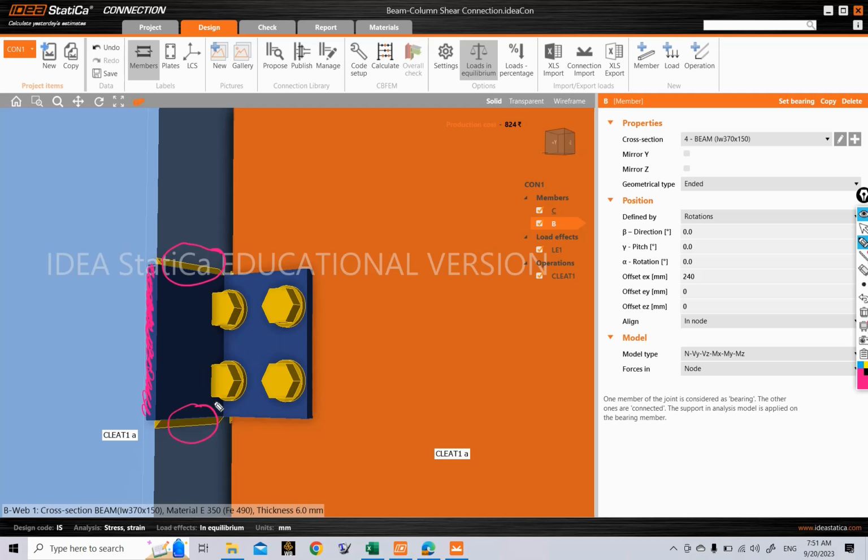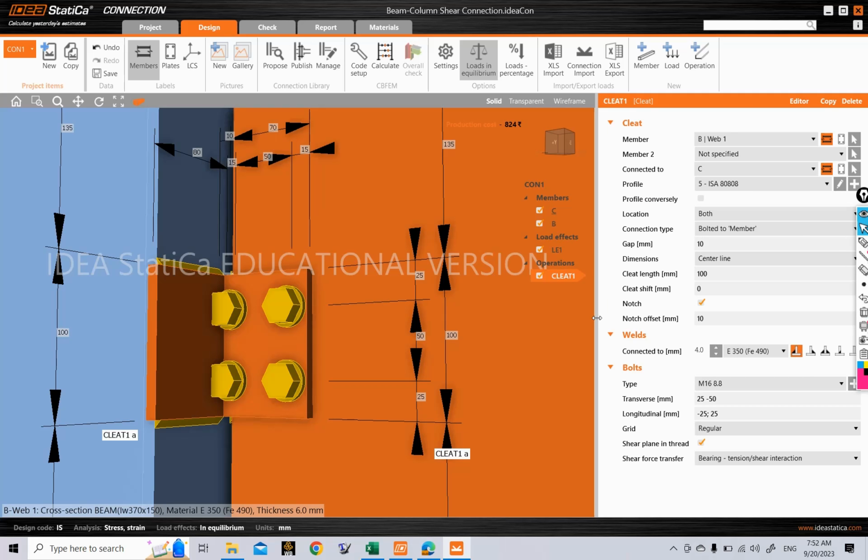So we have to change the parameters to make this, and also we used 2 bolts here, 1 bolt here and 1 bolt here in a single line when we are designing manually. So we have to change the number and location of our bolts also. So to do that, let me again click on this Cleat 1 option here. So for currently welding, what is happening is you can either weld on this side. If you choose this fillet weld front side, then welding is being performed there.